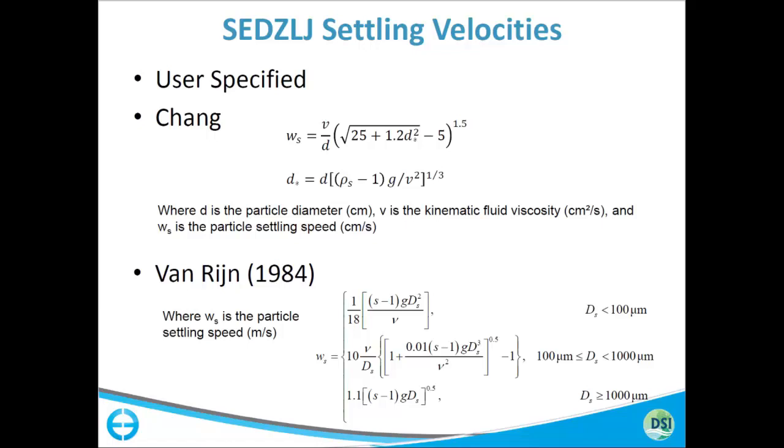That's the density of the solid, your grain specific density. So really what you're looking at is the difference between the density of the water and your sediment grain. Just noticed that, sorry about that. Anyways, and viscosity. So you get this representative D star, and it goes in the equation. You can calculate here your settling velocity.